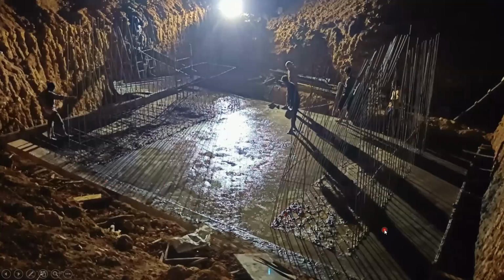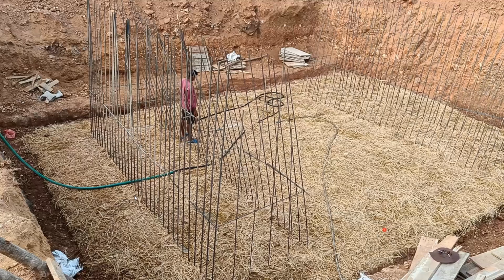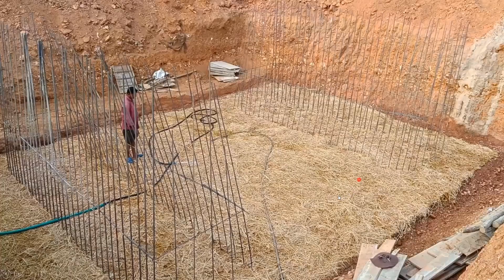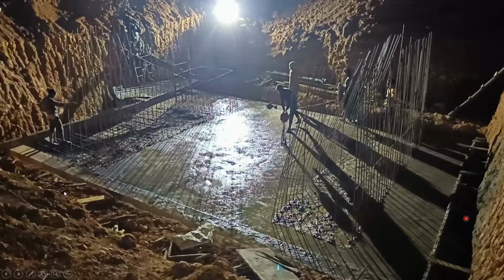You got an idea how this is created, and then this is a grass what we have put, since it's a huge area. You could have put a gunny bag over that and done the curing. But what these people have done, this is a grass what you get. They have put grass everywhere, and then they have sprinkled water over that. So that water will be absorbed by this grass, and because of that the curing is going to happen there. Okay, got it. So in this way, and then whatever soil we had, whatever side, this backfilling we have done.